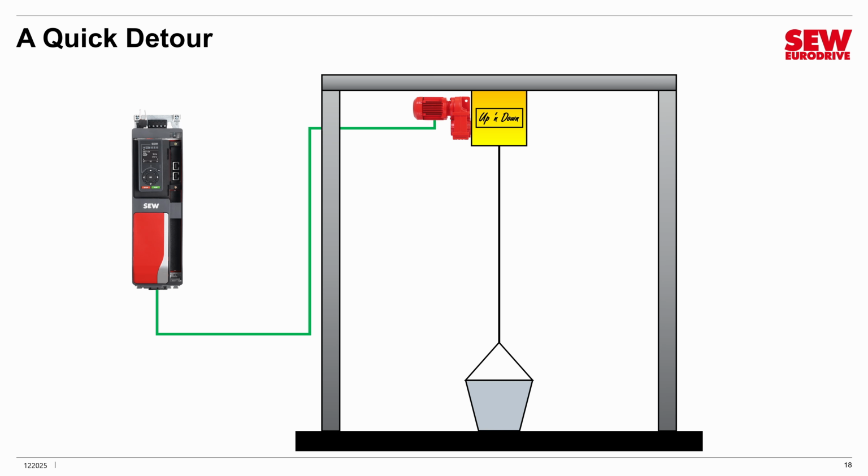And it goes by a name that you probably are familiar with if you know anything about VFDs. We call this regenerative power. It's because the motor is generating energy that goes back into the VFD. Now, regenerative energy doesn't just happen with hoists. It can happen with sloped applications like angled conveyors. It can even happen in purely horizontal applications if you've got a large, massive load. The momentum of that load makes it hard to stop, so when the VFD is slowing it down, regeneration can happen then as well. So it's actually a very common problem in many applications.